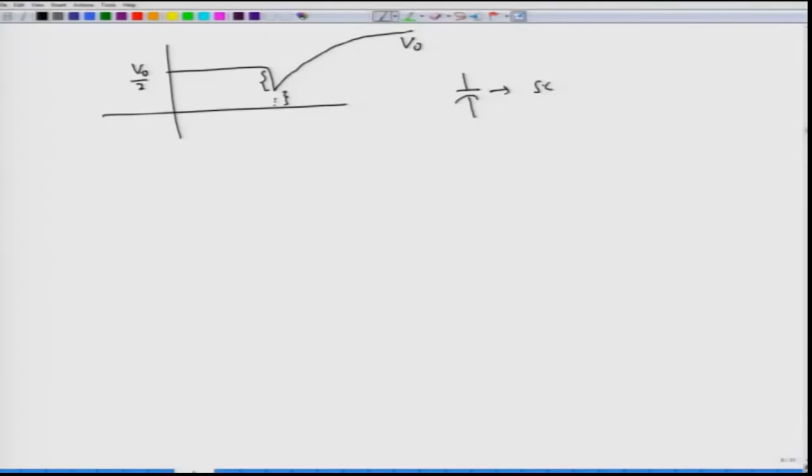Eventually the capacitor will start to charge up to the full voltage and becoming an open circuit. So what you should have is not just a capacitor but also a load resistance RL, and the amount of jump that you would see would clearly be the voltage that the load RL will carry.